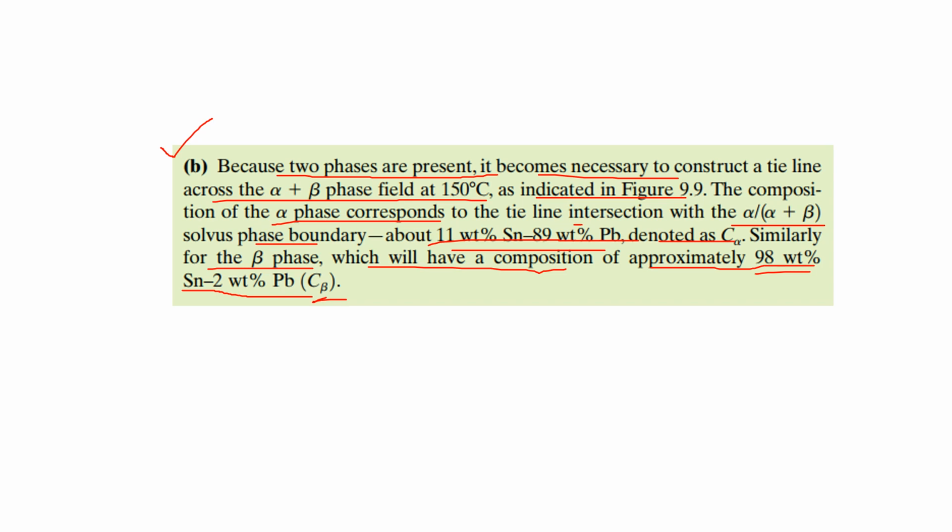In the exam, the question may be changed to find the composition, say at 60% lead, 40% tin. Find the composition at that point, find the phase region, and say how many phases are present. In the exam, the question may be changed to find a composition and phases.